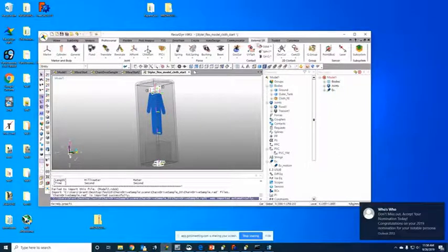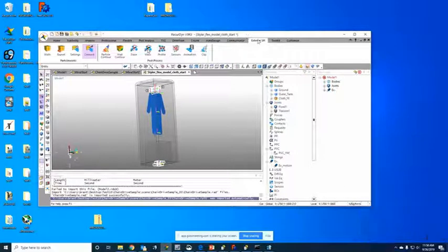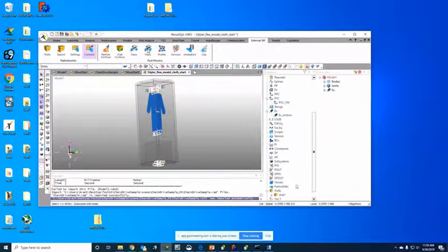And so I'm going to go into this external SBI tab, and in the window here, go ahead and select the wall. Here I have as a default the surface patch set. I want to change that to body and select this outer tank. And so that created one of the walls that I need. I need a second wall though for the FE body. So I'll click on the wall again. Instead of selecting the body, I'll select the surface patch set.